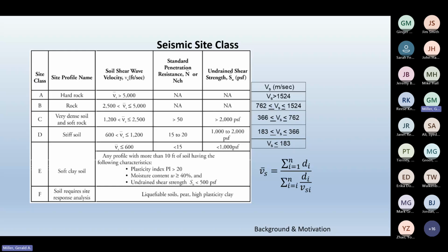And then finally, you can look at the weight averaged undrained strength for clay soil profiles. So SPT N values are quite simple to use and often used, but shear wave velocity is probably a more precise way to analyze seismic site class. Those of you who have seismic cones, I know Jim does. Do you have a seismic cone? Everybody does. Maybe you've used Vs to estimate seismic site class.